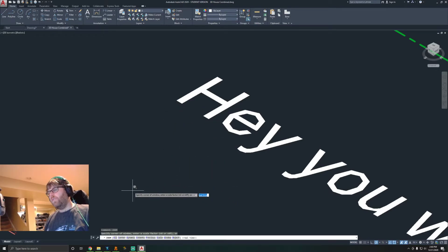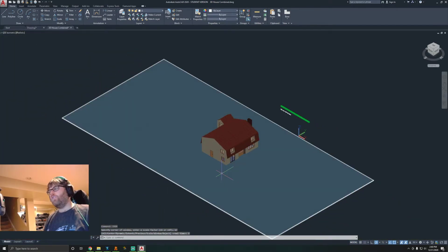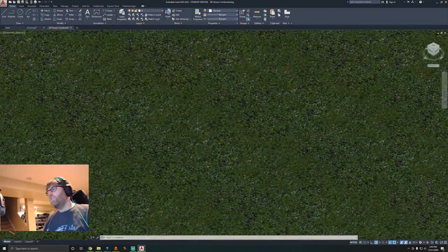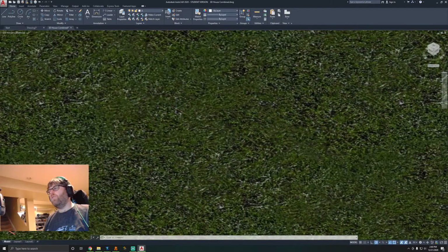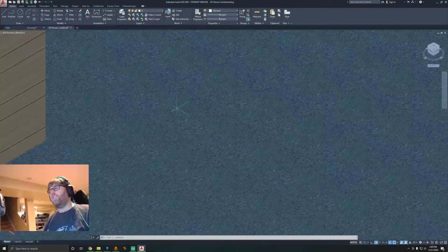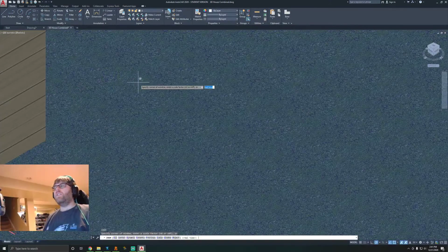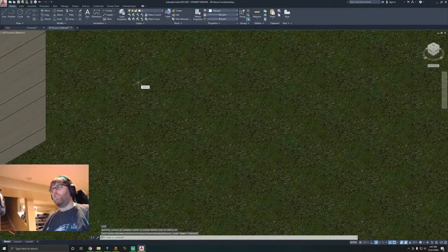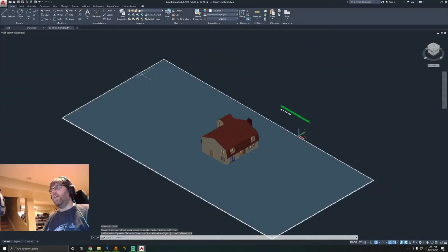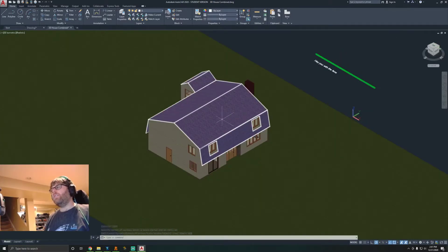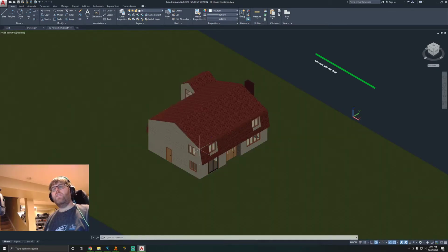If you wanted to zoom the extents of the drawing, you can do zoom extents, and that's everything that's drawn. Sometimes zoom all is also similar to zoom extents. There may be a drawing at some point where you zoom in and you're using your scroll wheel and it just won't advance past this point, and you're like, why can't I zoom out more? The easy fix for that is to just type in zoom, enter, and then all, enter, and it kind of resets it for you and it zooms out to everything you wanted. So if you ever get stuck in that predicament, you could use that.